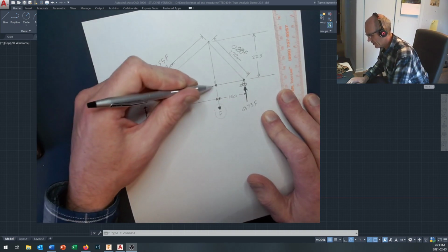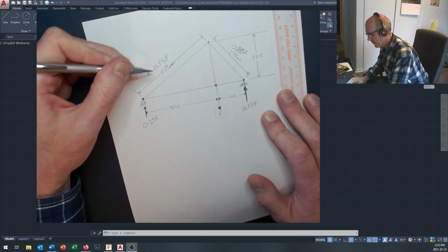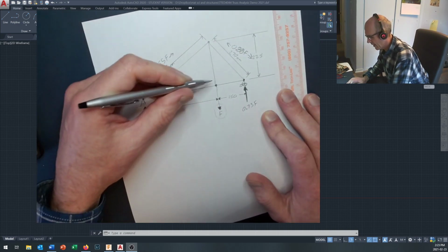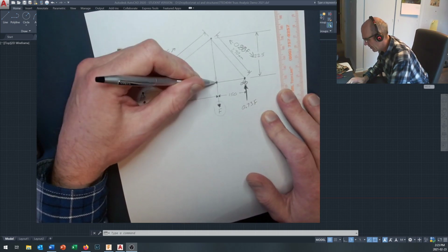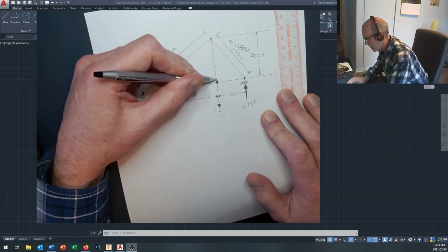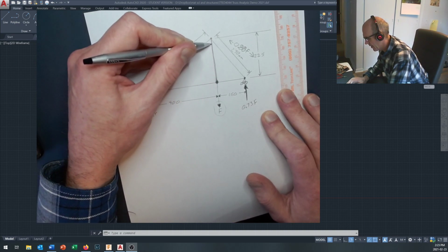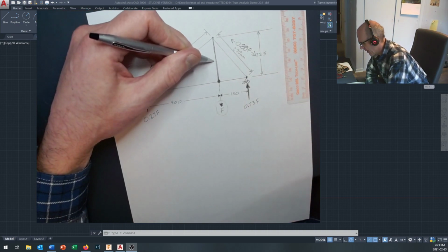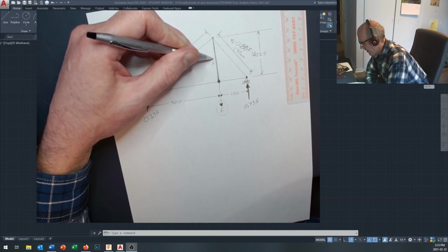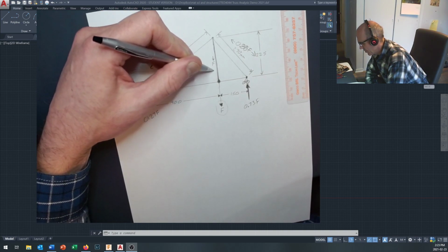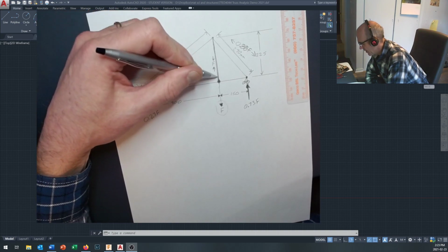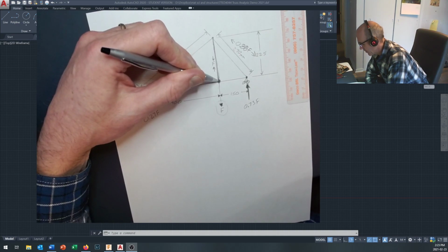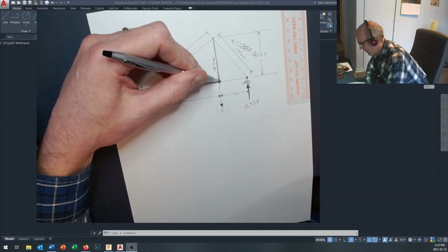And to calculate the force in the bottom, now keep in mind, these forces are both going to be in compression. If we've got a node coming up and down right here, we can't really just have one node right here without a member coming up and down in the middle, and that node is perfectly vertical, and it's going to have F acting in it, and that F is going to be acting in tension. So we do need a member coming up and down right here because this node can't support any vertical force without it. We need something lifting up on that node.